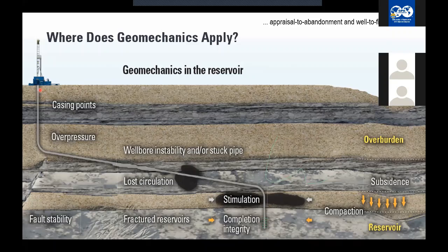So you need to determine the weight of the mud that you are going to use. The other applications are, you might have heard, some incidents in the industry where a blowout has occurred. A blowout is a phenomenon where the fluids inside the formation, hydrocarbons inside the formation, leak into the wellbore and rise up with a good amount of pressure and catch fire, right? It can lead to safety events. It's a dangerous event that everyone wants to avoid.